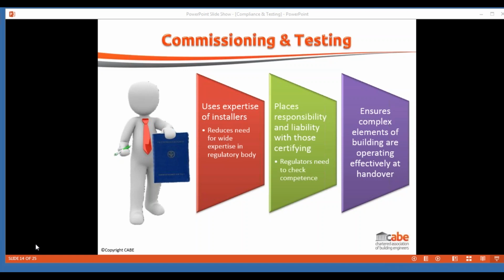Because when we look at air pressure testing, to achieve an air pressure test in a new dwelling of something like a leakage of 10, it is possible still to have a gap in the construction equivalent to the size of about a 20p piece for every square metre of the external wall. So yes, if there are some seals that have been damaged, it would compromise the result, but it might still have passed a test or given a figure that enabled the calculation process to work.